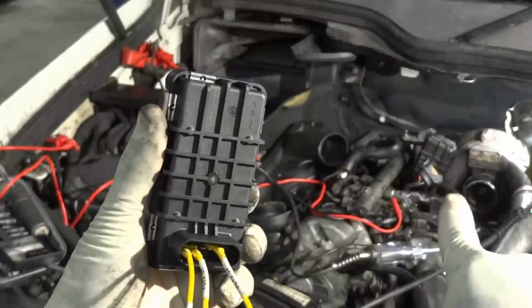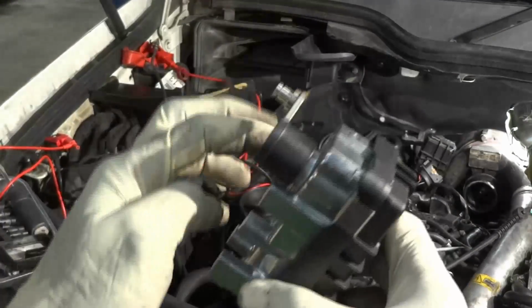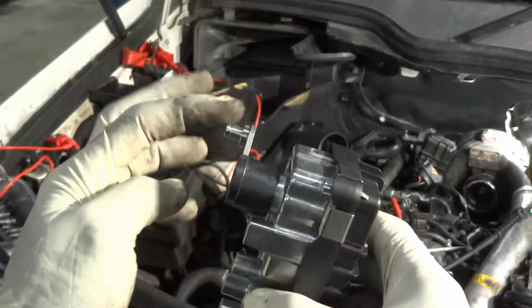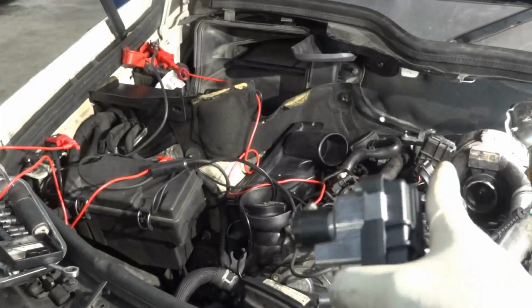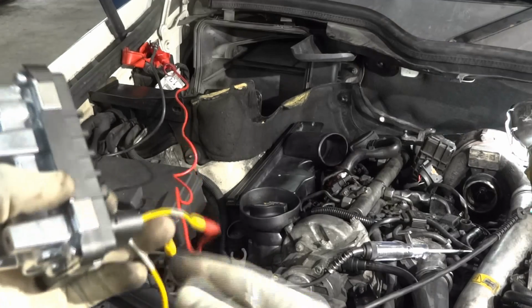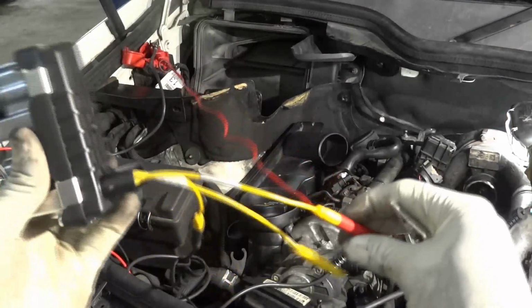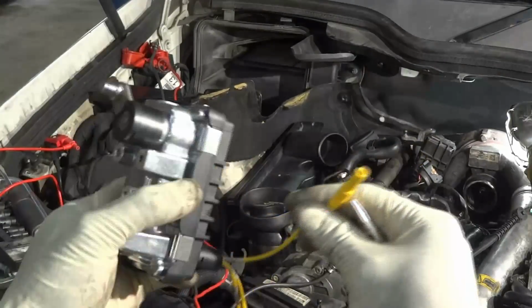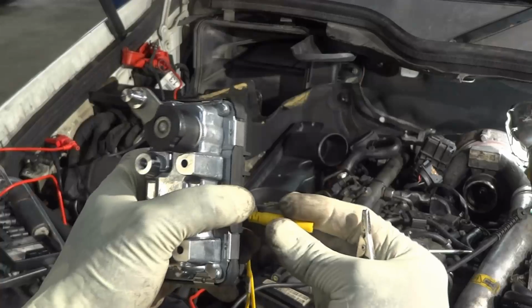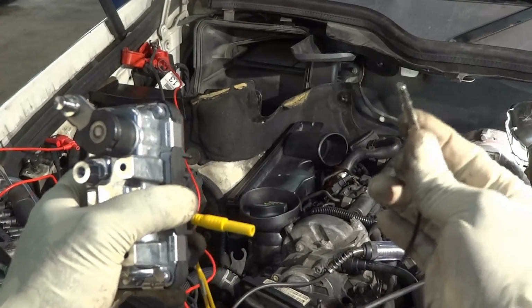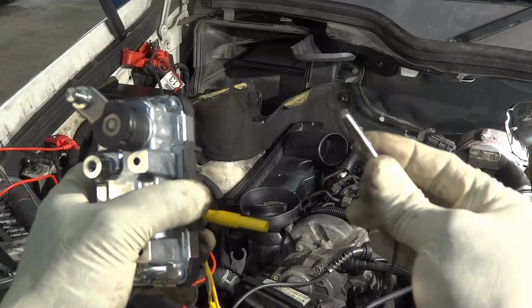I did the same thing on the actuator over there. I couldn't get this to turn. So let's do the same thing on this and see if this can turn. If this does, then we will know that that actuator is bad. I got my power going to this connector and then the ground here, and then this is a ground. So I'm technically being the computer here.